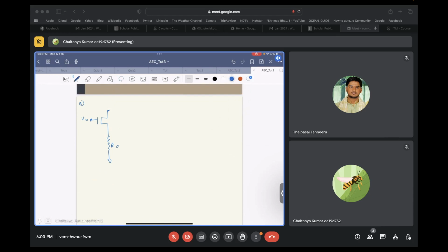the small signal model that we have studied so far in the course. First of all, let's say this is a structure, and we want to find the looking-in impedance Rout over here. Let's say this is a transistor with a transconductance of Gm and output resistance of R0, and there is a resistance at the source of this transistor. Let's call it Rs. We want to find the looking-in impedance from this terminal. Let's call this Rout.